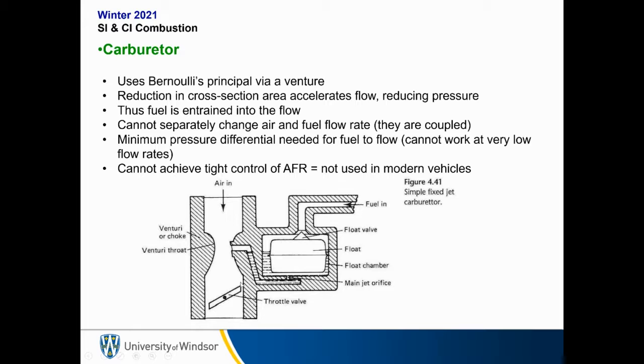So with a carburetor, if your engine drops below a certain RPM or a certain amount of air inflow, you're not going to have any fuel and the engine's going to stall. So generally, you can't have very low idle speeds. This is worse for fuel efficiency and also for emissions. It's also bad because we can't achieve tight control of the air-fuel ratio, and this is bad, again, from a flame propagation and also emission standpoint.